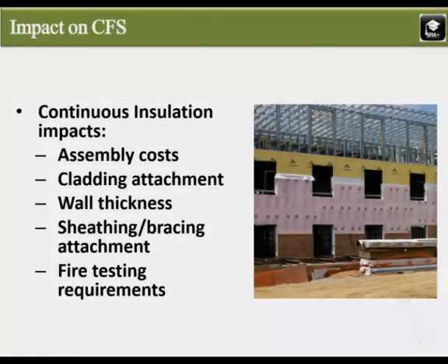Probably the highest impact issue with regard to cold-formed steel framing is the addition of continuous or foam insulation on CFS walls. Although there are simple ways to comply with the requirements without continuous foam on roofs and crawl spaces, it is much more difficult with walls.